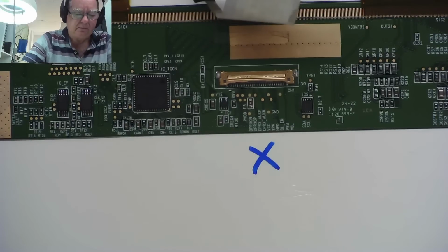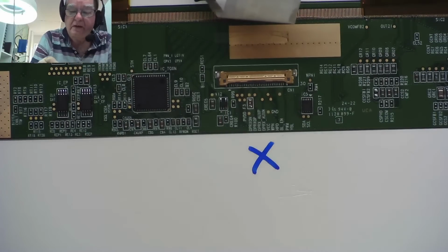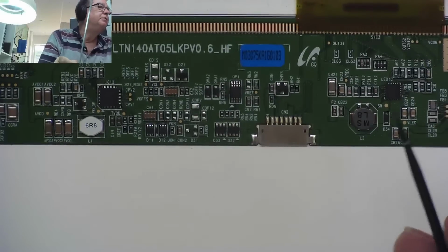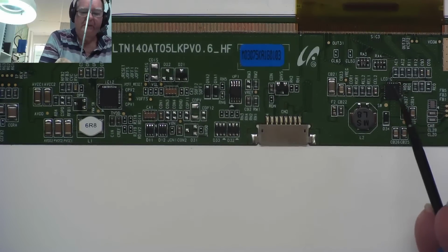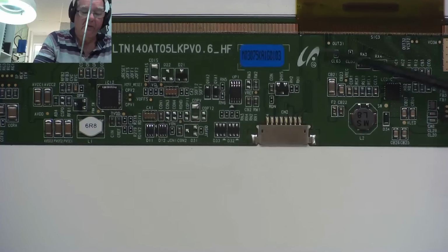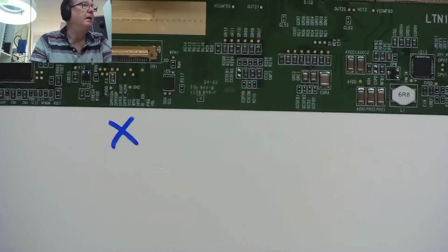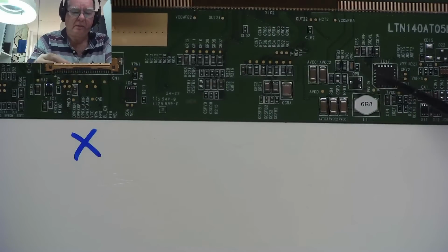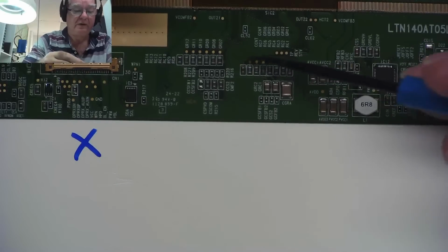So there's a few more chips here, a couple here, there's another one here, there's a few over here. I think this one at the end you can't see. This one at the end here, and the fact there's a buck regulator coil here, that's probably a controller, and this will be powering the LED backlight. So I think all the stuff around here is to do with LED backlighting. This one we know, or at least I know, I'm telling you, is to do with gamma correction, to do with these resistors here.